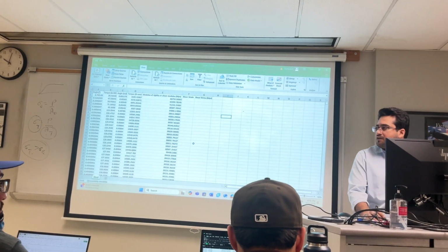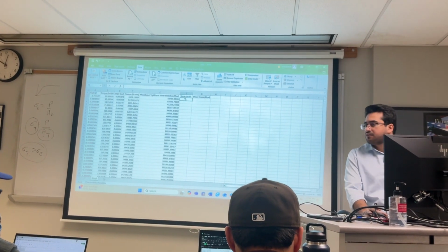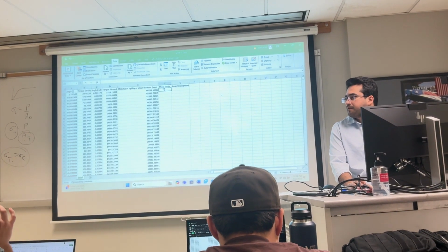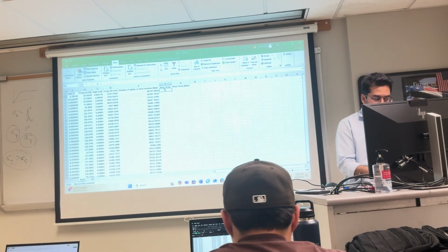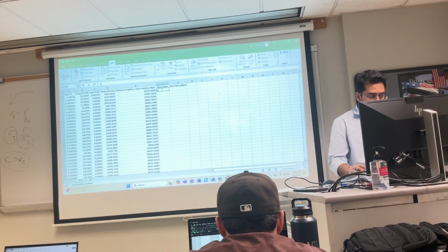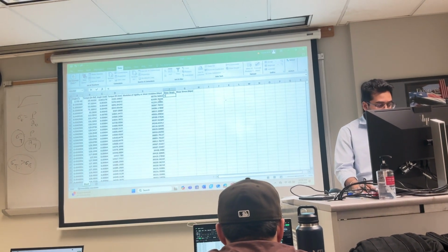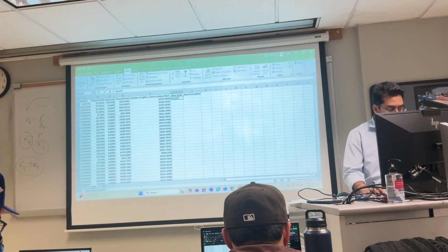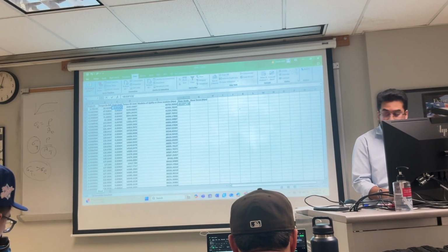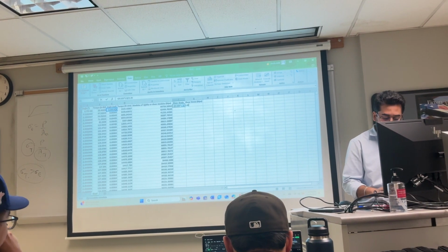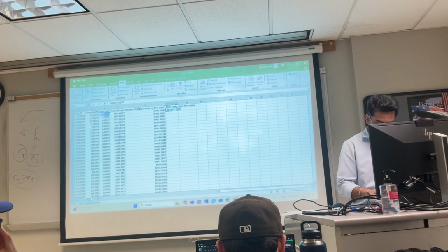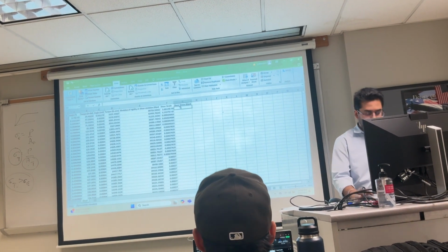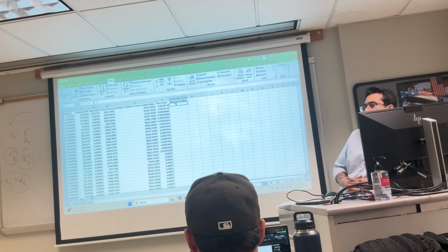Now just see. So shear strain is R theta by L. What is R? It's diameter divided by 2. 9.525. So it is equal to R theta. So you can say 9.525, then multiply by theta, which should be in radians. Close the bracket, divided by L. L is 304.8. Good? Yeah. 368.